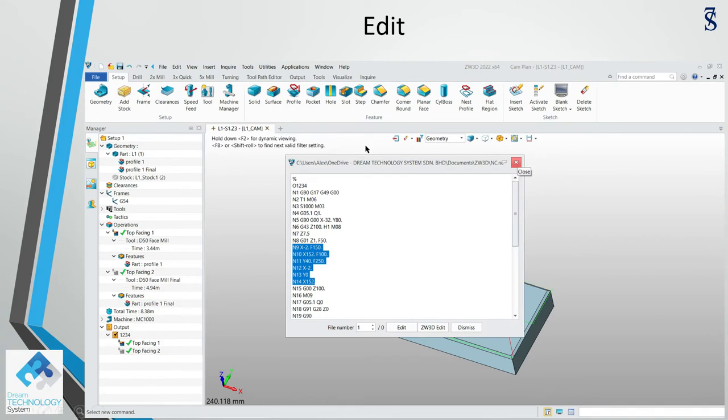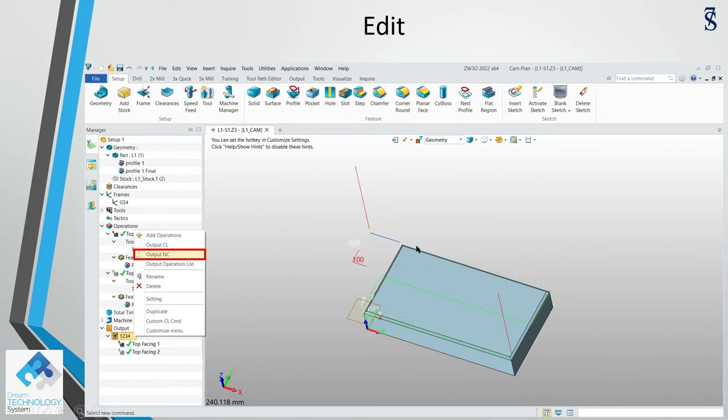The NC shows us that the feed rate seems not steady until block 11. So we have 150 and 100. This is because of the slot cut. Meaning to say, I go back to see. This is the slot cut, and the blue color is the engage. So we need to change this tool feed rate to the standard tool feed rate, so that we don't need to slow down the engagement and slow down the slot cut.